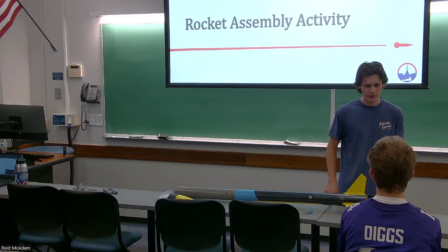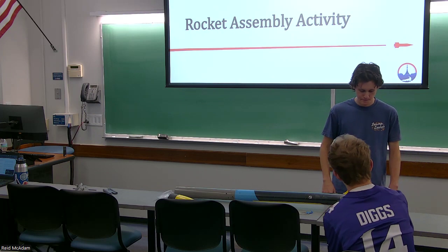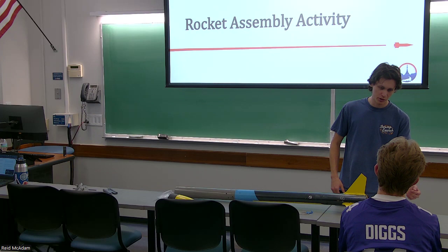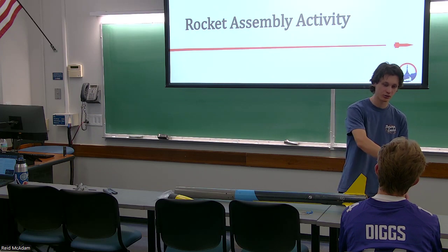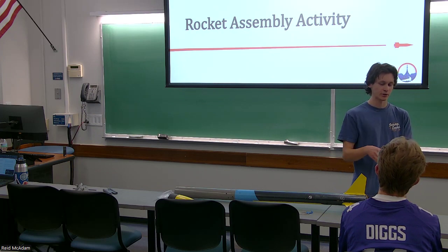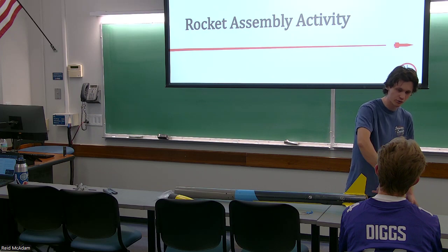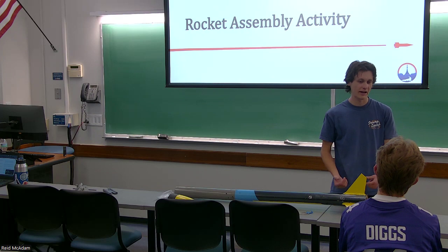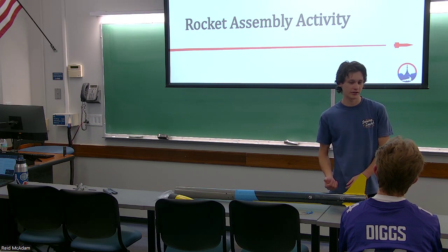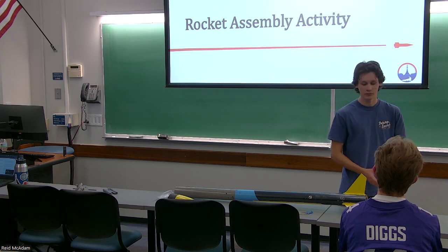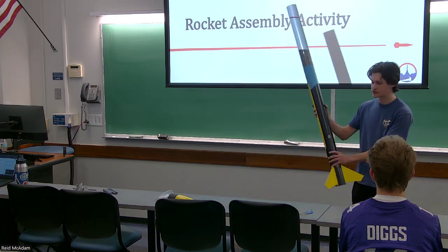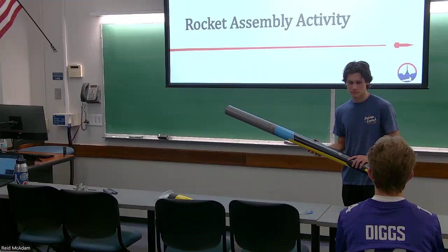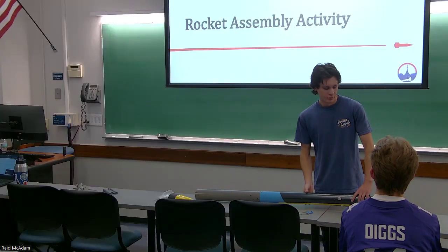Wait, sorry, can you repeat that? Is it just for the bottom right there and not farther up? Yeah, just the bottom here, because when you push the motor in, it has a little stop. The stop that's built into the motor stops it from going too far in, but then it's meant to just slide in. So when you first slide it in, there's nothing stopping it from just sliding back out. And when it's on the launch pad like this, gravity's going to pull the motor out.